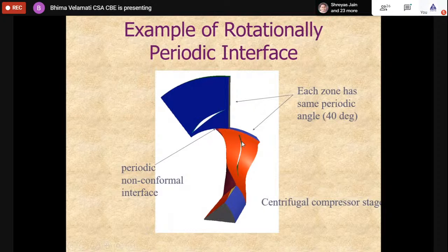There are concerns because when I'm solving for a reference frame around this blade, which is solved as a rotating reference, I would solve a rotating Navier-Stokes equation. Wherever you have stationary, you will solve a stationary Navier-Stokes equation, and you will interpolate the solution at the interface. This looks fine, but the only consideration is the solution is steady state. There are a lot of unsteady phenomena that occur because of rotation.